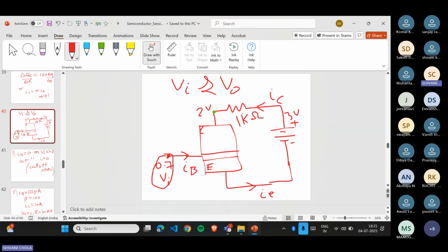See, you are correct. But the value which you are calculating, V equals IR, is the potential used by your resistor. So 1 kilo ohm multiplied by 3 milliamperes gives you 3 volt, right? But what does it tell you? It tells you your resistor now has used the 3 volt of energy. And if you subtract 3 from 3, you will get 0 over here. All right?